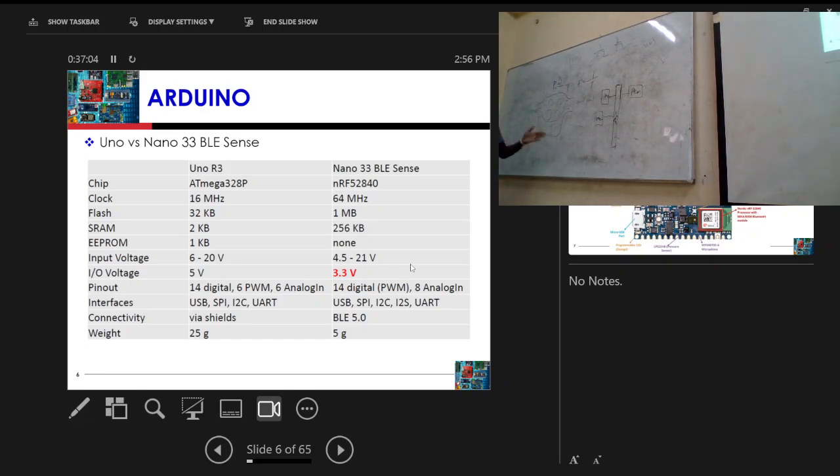If the time is so long, what happens to the frequency? Common sense, yeah. So the frequency will be smaller. Common sense, right? It means that if you design your digital system and the delay path is so long, you are not a very good designer, right? Because it takes so much time for the signal to get from the input to the output. So the frequency will be smaller.